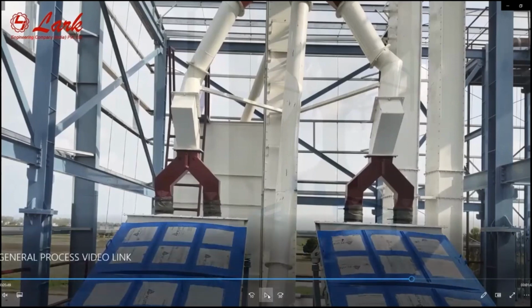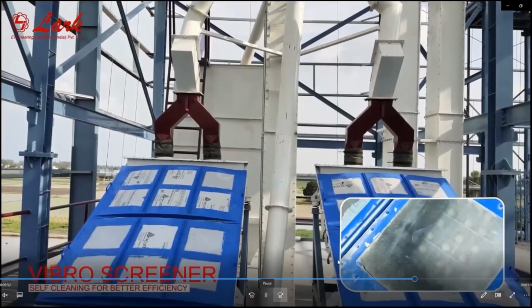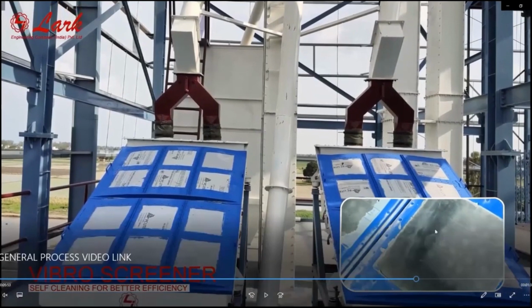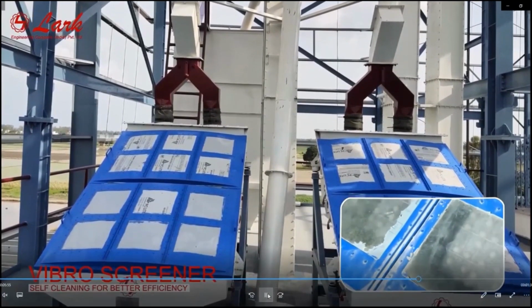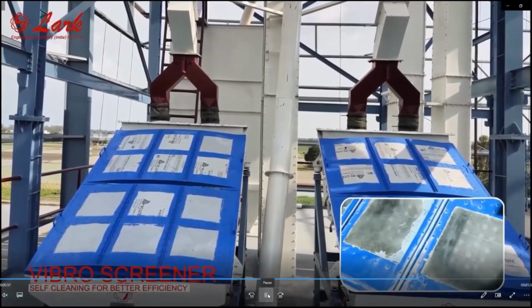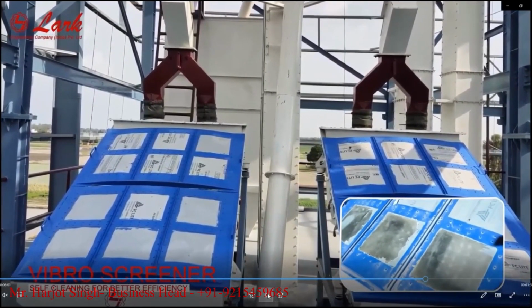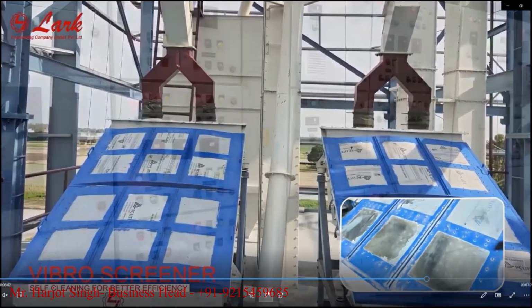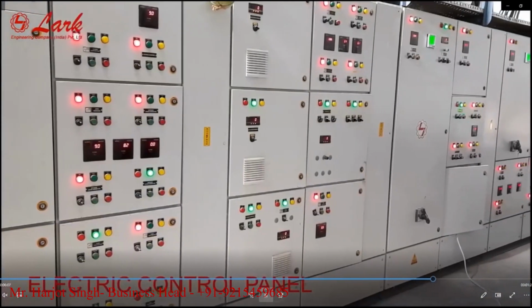So auto cleaning screens help. You can see the vibrating rubber balls are there to clean the screen automatically, so that they can work at over 90 or 95% efficiency. In general, with less cleaning, the screens only work at 40 to 50% efficiency after 1 hour.